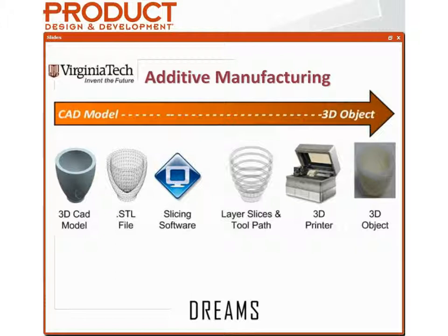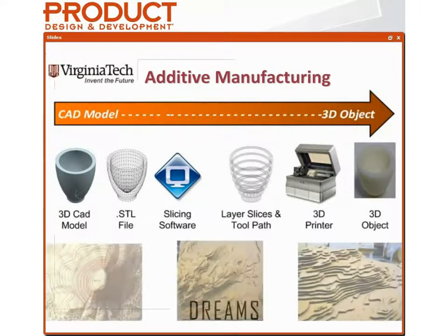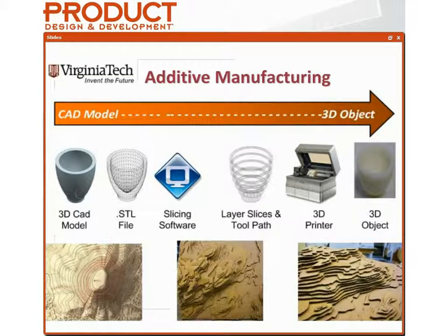In effect, the original idea came from these topology maps, where we had a challenge, which was how do you create a 3D object, and the way it can be done is by representing it with a bunch of stacked layers. Now, again, there are a lot of different technologies on the market that all fall under this umbrella of additive manufacturing, and the only thing that differentiates them is the way in which they create each layer, but they all create the first layer at the bottom and then build upon that layer by layer from the bottom up.